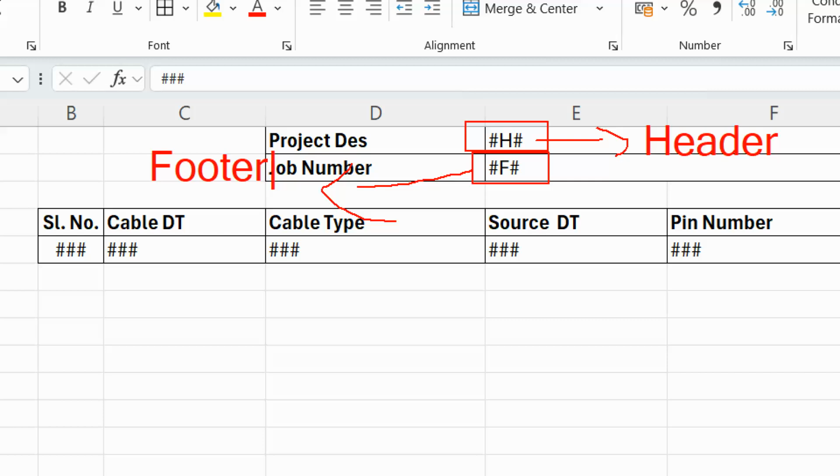From there it will fetch all those details. Similarly, when you see 3 hashes, this means it comes from the label tab, and each 3 hashes corresponds to one property. For example, if I take hash dash hash, that means you are taking 2 properties in a single cell. So it all depends on the way you want it. So 3 hashes corresponds to one property.